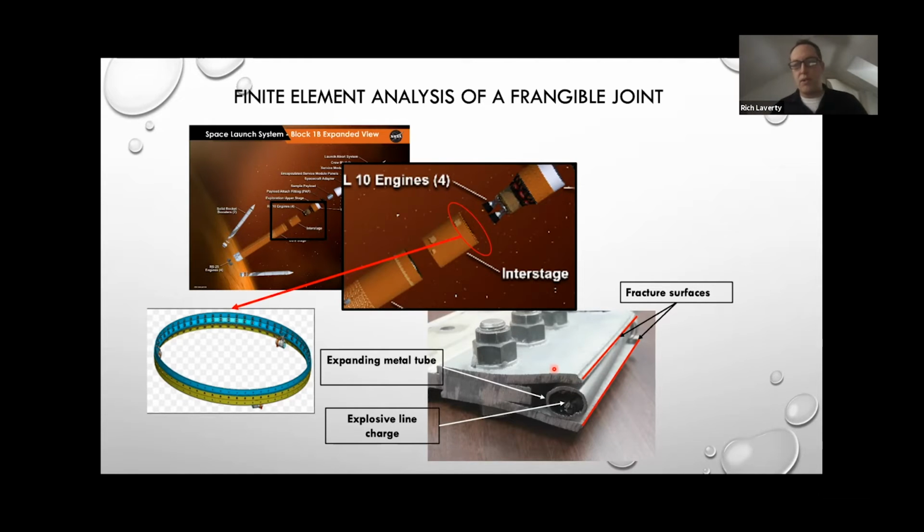Every design variable has a very specific value, but in production, you can never achieve that exactly. So there is an interval in which all these variables reside, but you can't know in advance what they are. Like the notch, it's cut with a CNC machine, and we can get it to say 1/10 of an inch, but it's 1/10 of an inch plus or minus 1/100 of an inch.